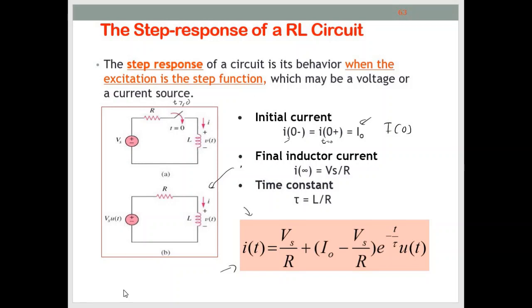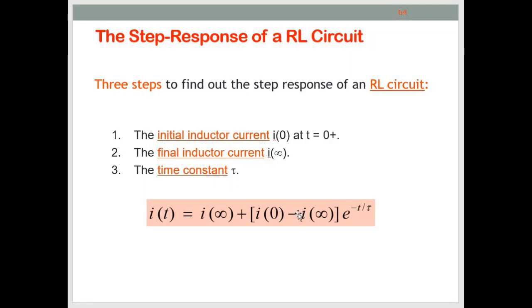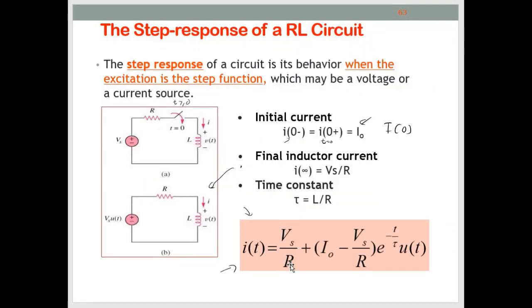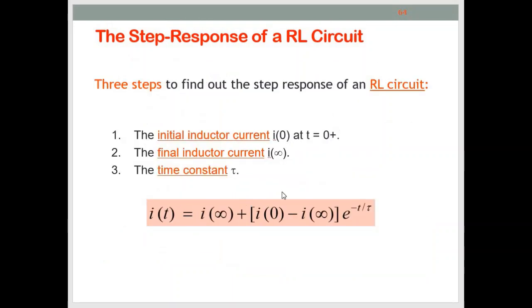For the general case, if the circuit becomes complicated, don't use this equation. Use these equations. It is more general for step response RL, because if you use this one, Vs over R, you must change the complicated circuit or whatever circuit to this basic step response RL. Better to use this formula. We will learn later on how to use this formula in the example.